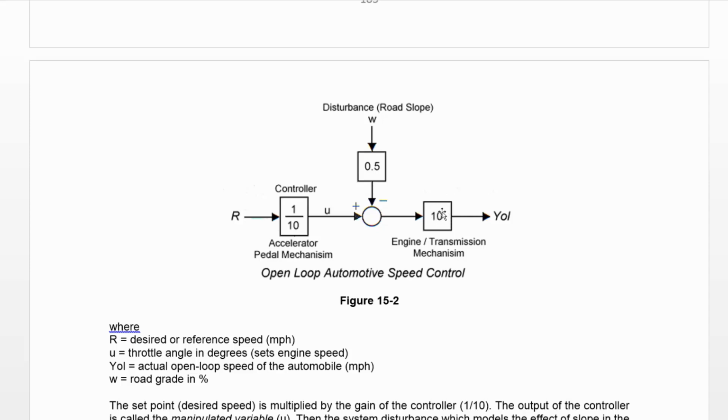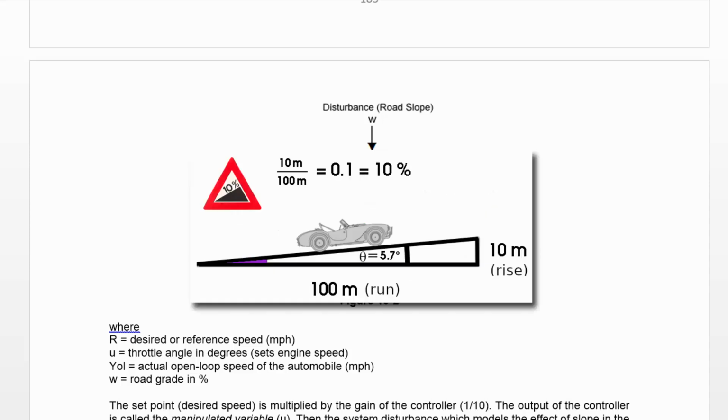Well, nothing's perfect. Nothing in the world is perfect. Everything has disturbances. A disturbance could be a temperature. You're trying to heat something up and it gets cold and it absorbs the heat out of it, or it gets hot and it puts more heat into it. Or it could be a flow rate, and the pressure of the system due to the pump speed fluctuates and the flow changes based on the fluctuation of pressure, and this pressure would be a disturbance.